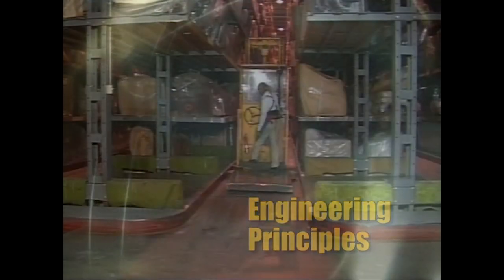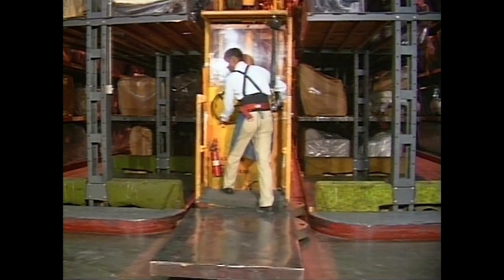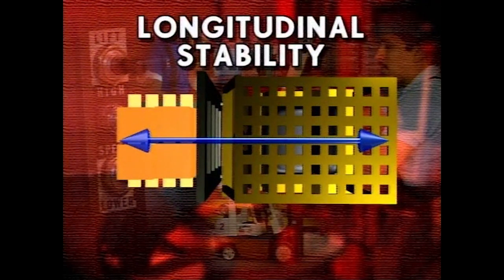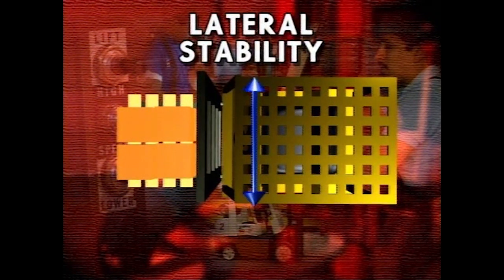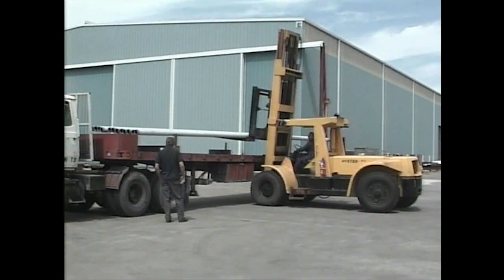We're not expecting you to remember too many technical terms, but you should be aware of some engineering definitions and how they apply to your particular forklift. First, there's the longitudinal stability. This is a fancy word that is the truck's resistance to overturning forward or rearward. This is demonstrated when you use boom attachments. Lateral stability is the truck's resistance to overturning sideways, as when using pipe attachments or extremely wide loads.